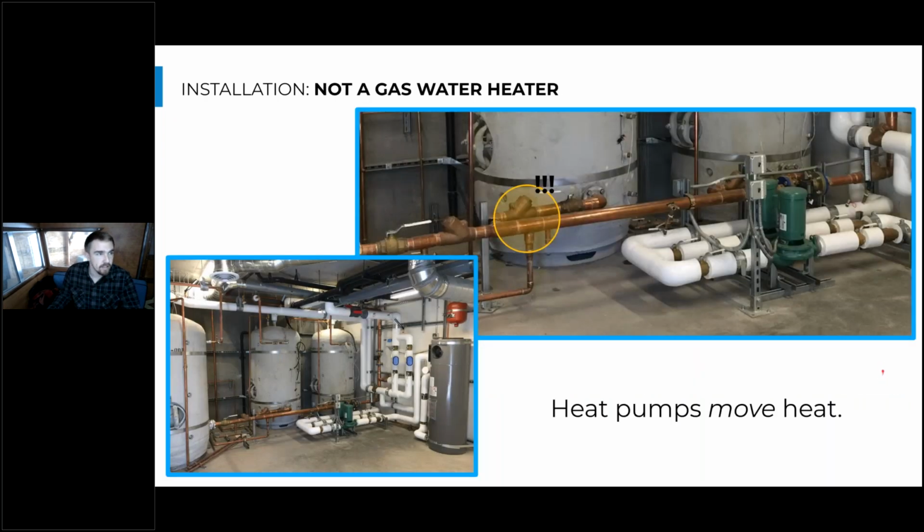And a big point here is that heat pumps are not gas water heaters. So you want to make sure that any best practices that usually don't shine through on designs actually apply to heat pump water heaters, because installers that have been working on these for decades have found a lot of really great tricks to use or ways to enhance plumbing designs that aren't quite as evident to the engineer or shown in the drawings, but they don't communicate with the engineers on these little changes that usually make these systems better.